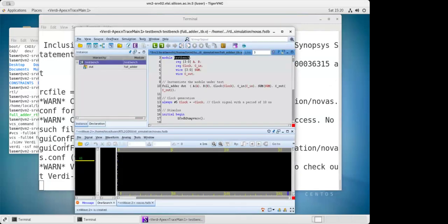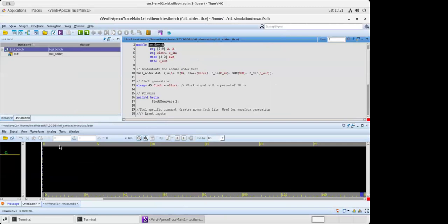So what I have done till now, I just pressed that command. Something automatically happened. One window has opened. In that window, you will see the same code has been captured here. Nothing is here yet, so this is the waveform part. I will show how you're going to add the waveforms here. This is basically the Verdi interface. In this Verdi interface, you have the testbench, you have the code, everything. Now you can play around with this particular part.